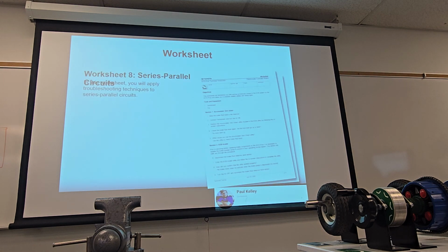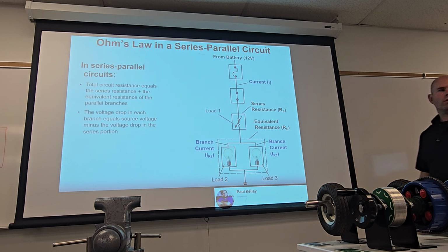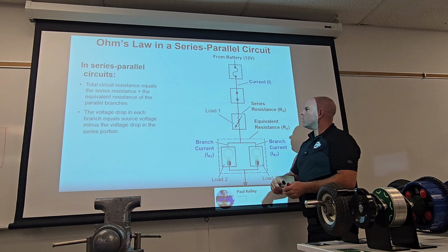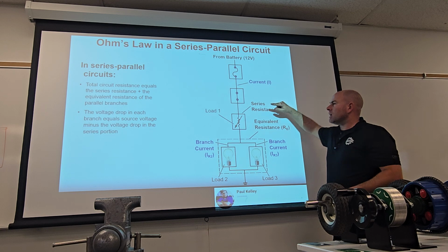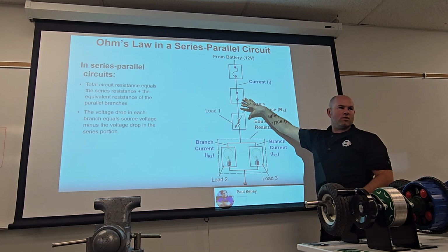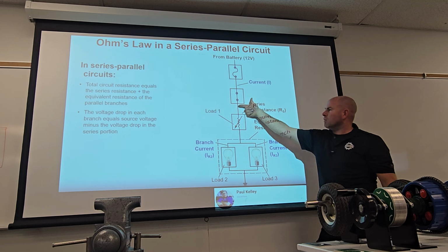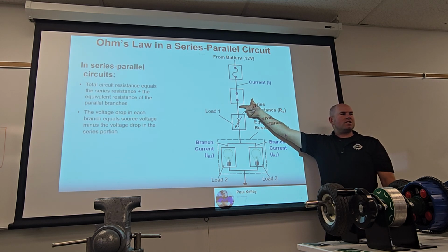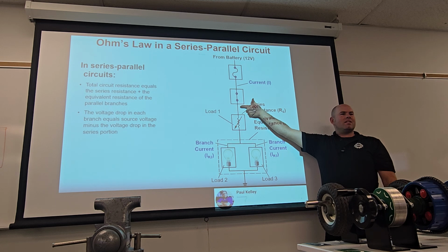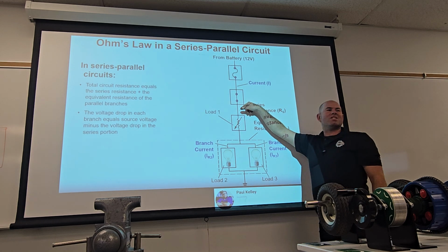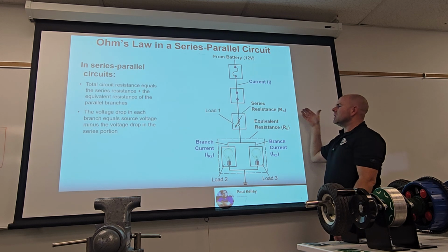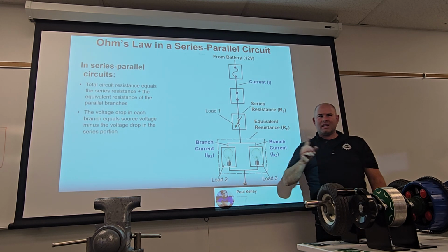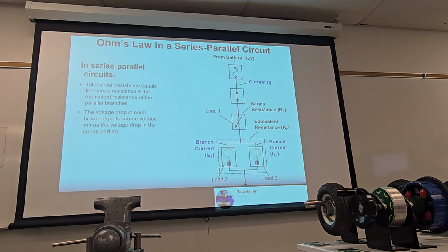Oh, but by the way, it also says it could be positive too. So mostly when we're talking about shorts, it's usually short to ground. But what if you took your car to Sparky's audio and radio installations and Sparky ran that screw in through there and it pierced a positive wire and then the screw touched right here and it was giving 12 volts all the time? What would the customer concern be? Come on, think about it. All the time. You turn the headlights off and the headlights are on. You turn the headlights on and the headlights are on. You turn the headlights off and the headlights are on because it's a positive short to the circuit. Not real common, but that's still a short.